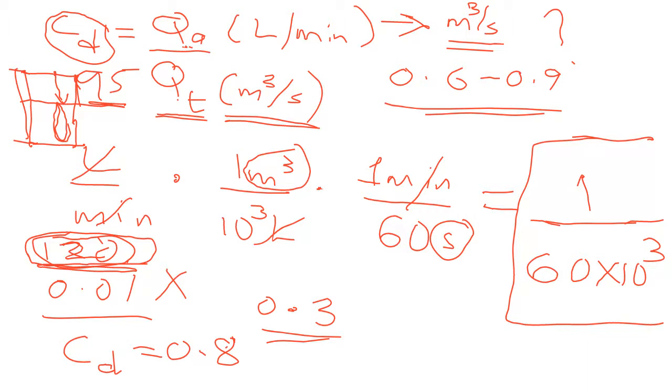You remember when we were discussing the mouthpiece, we said it makes the contraction coefficient 1. It increases the contraction coefficient, and that makes it better. The better the coefficient of discharge, coefficient of velocity, coefficient of contraction, the closer it is to 1, the better. Because that means that the hydraulic structure is very efficient in measuring the flow rate or the velocity or whatever parameter you are discussing. It makes it very efficient.